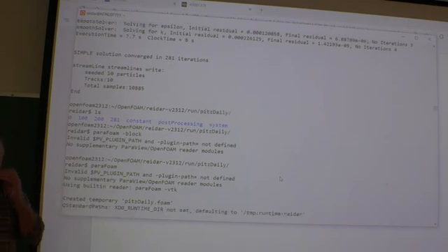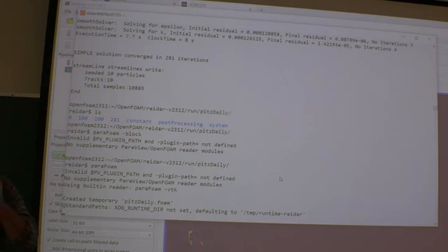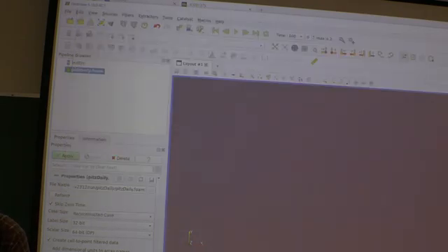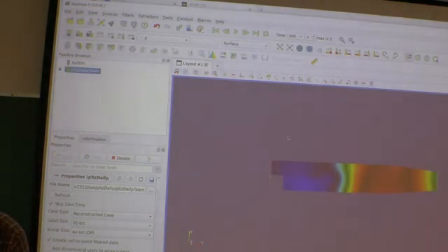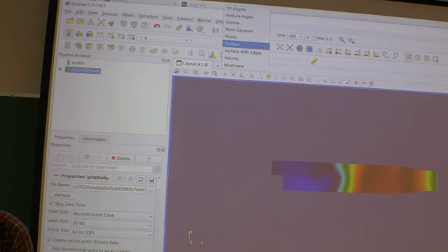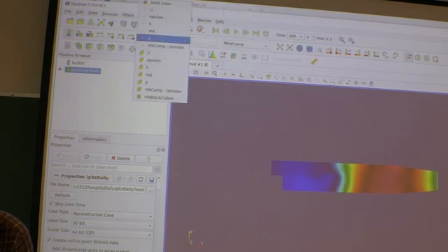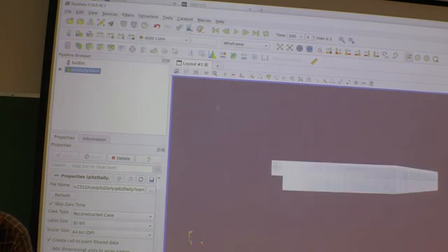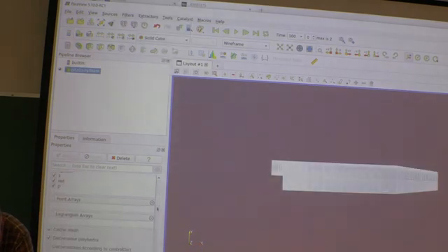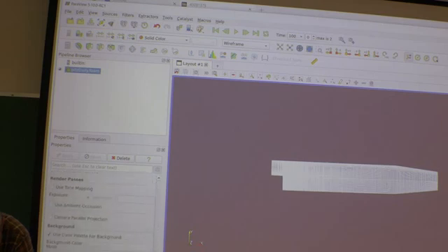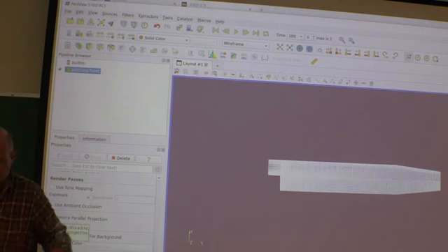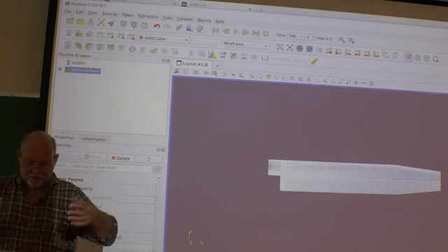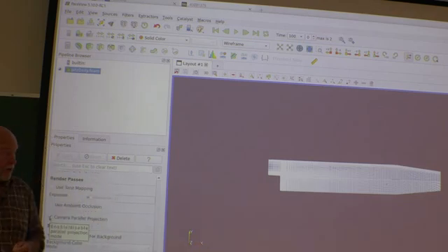Because the mesh here in this tutorial is not the easiest mesh. So let's just click apply here. We can have a look at the mesh. Just only look at wireframe and a solid color. And when you want to look at the mesh, then I will recommend you to switch on camera parallel projection. Then you get rid of this 3D effect. I mean, it's only a two-dimensional mesh, but the 3D effect will distort the view a lot.